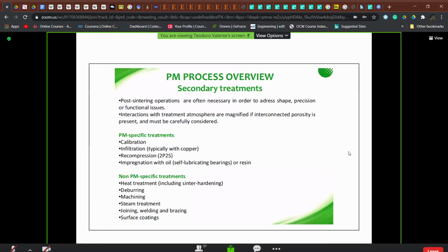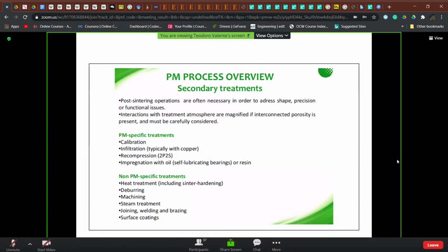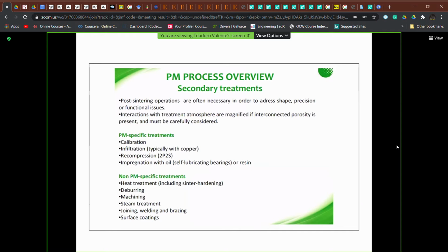After sintering, we have got our final component in a net shape, and we need to design, depending on the pre-compaction pressure that is used for the green body, also the expected shrinkage, because our final component is that obtained after sintering, not as a green compact.